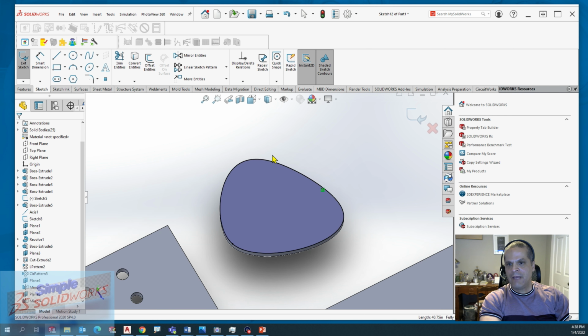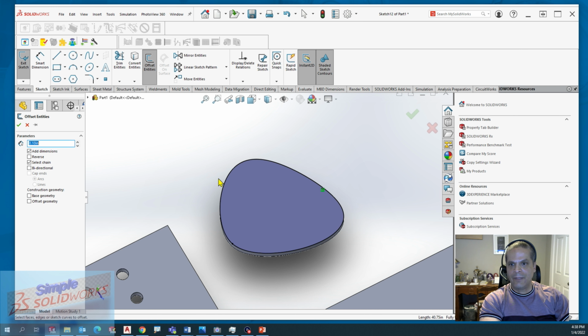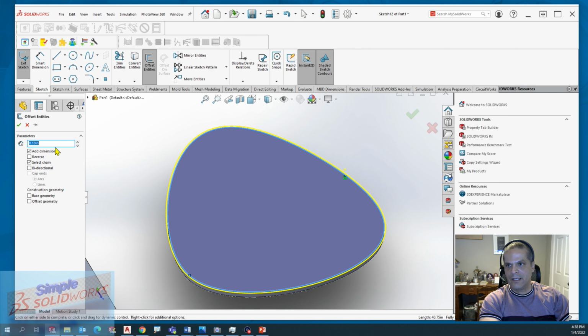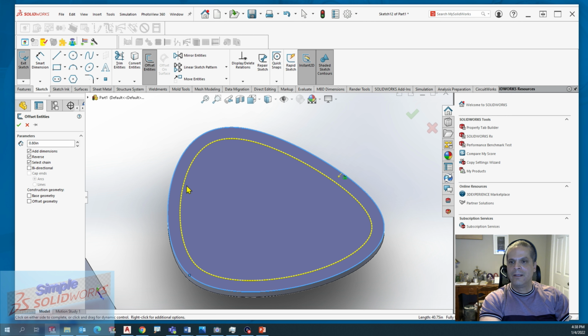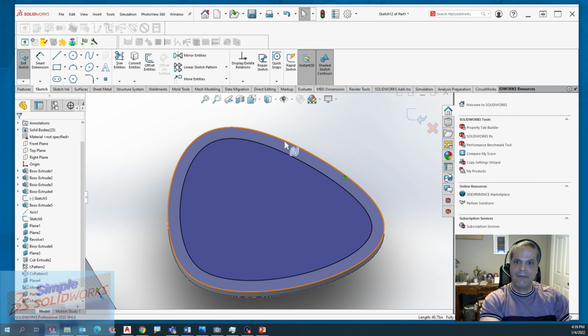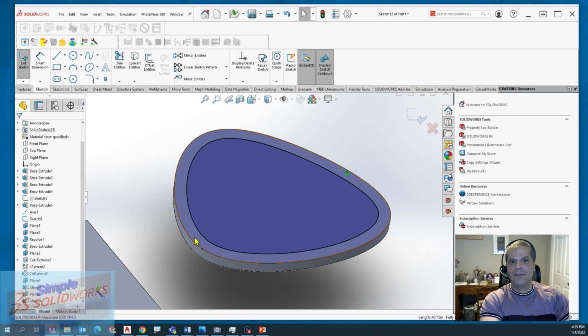Since I know I need to have a distance, you just don't put a hole in there and make it go crazy. I like to offset that. So I click on it and say, I need you to offset it, reverse that, go inside, because I want my pattern to follow that around like that. So you create that, and you have an edge where you can have things going on, right? Then you can confirm that. Now you have something to work with.